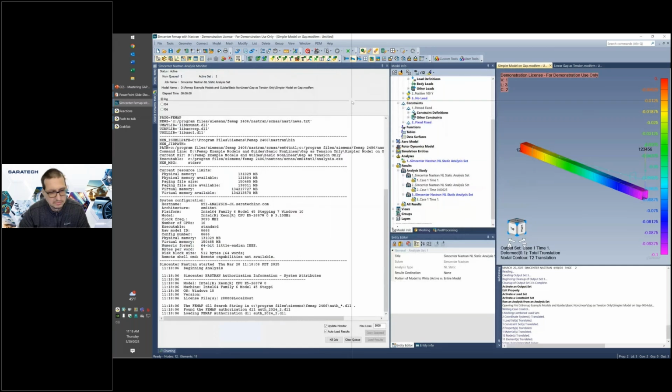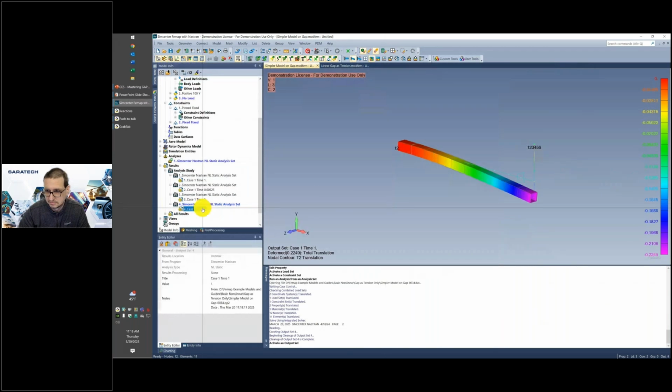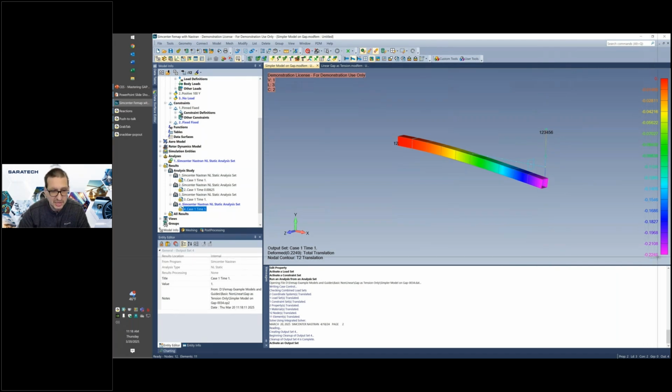It takes a moment. All right, so now we've got some of our beam deflection applied. We can see that our preload, even though we're in compression here, pushed the model down. We got a small amount of deflection of 0.2249. We do not end up with the full 100, well, sorry, I apologize. It's going off on a different subject there. Got ahead of myself. So we are seeing a bit of deflection on this model from the force preload in the compressive. It is pushing it down, kind of what you would expect with a preload.